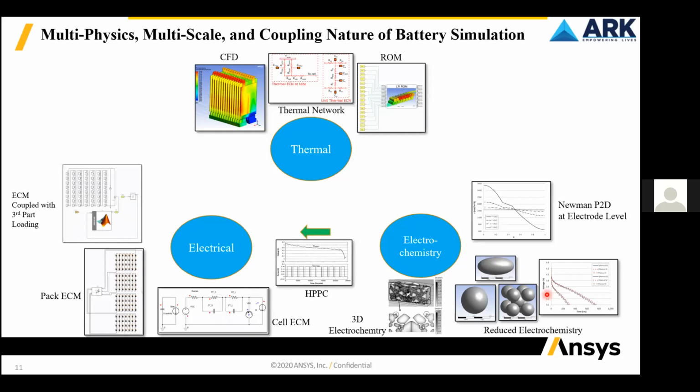But as I said, due to the small length scale associated with electrochemistry, it is a practical simulation tool only up to the electrode level at most, so you cannot go beyond that. Therefore coupling of different physics becomes necessary for any application beyond a pair of electrodes. So when it comes to battery cells, you definitely have to go for the coupling of multiple physics together.